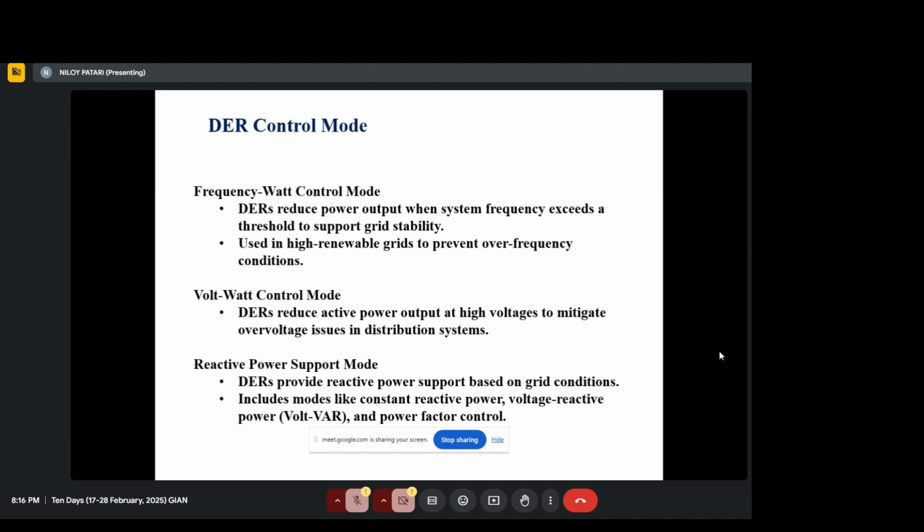Now, if we represent that reference power as a function of frequency, then we are trying to inject active power following that reference power curve, right? So we can inject active power in such a way that it mimics a frequency related curve. It's a function of frequency, right? That way we can stabilize the grid. Generally, it's a transient stability kind of operation. So we can improve the dynamics of the system. We can improve dynamic stability of the system.